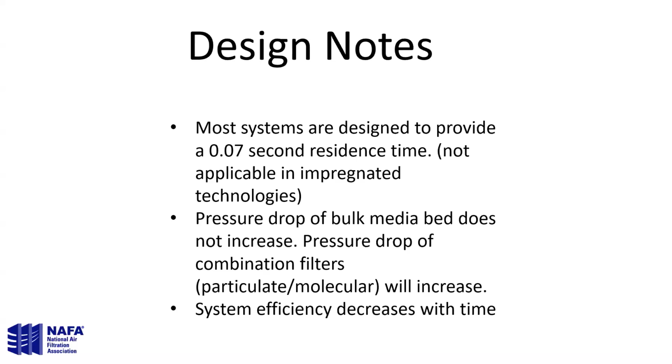It's because you're blocking the panel. And it can become a very effective filter if you let it build a ton of dust on it. But it gets to be a very expensive particulate filter. The pressure drop of combination filters, those that are using pleated media, those do increase the same way a particulate filter would increase.